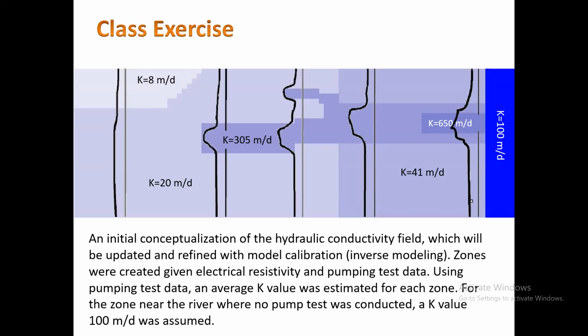Yeah, it's H. That's the only unknown in this equation, right? Because in this equation, we define our hydraulic conductivity, and that's how it's changing in X. Okay, and then we want to solve for H. To do this numerically, not analytically, we subdivide our model space into cells.